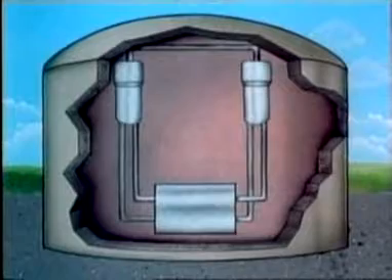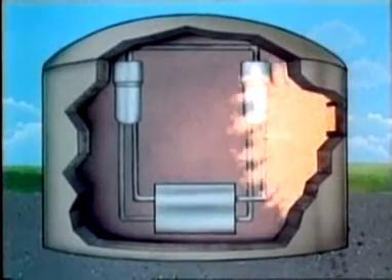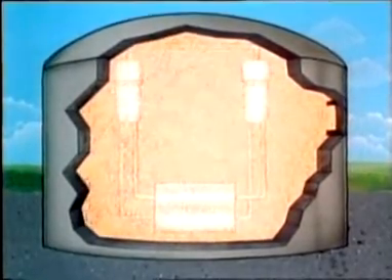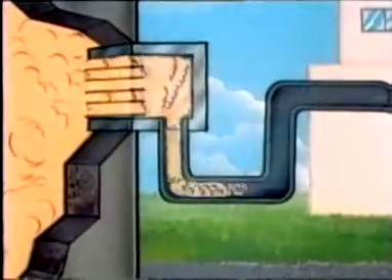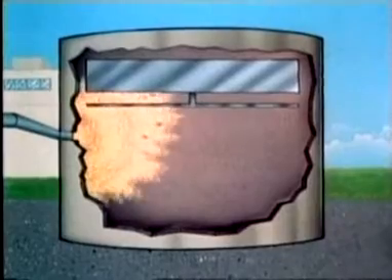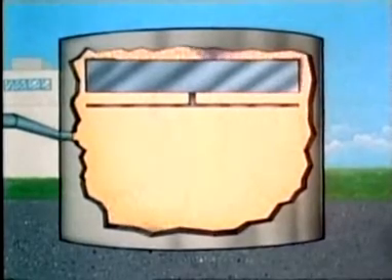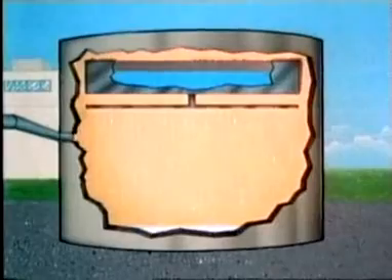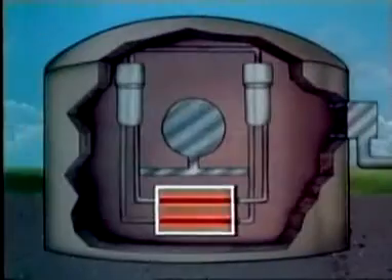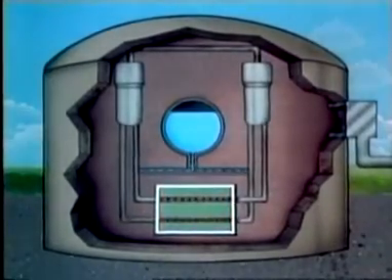One of the worst things that could happen to a nuclear reactor is a loss of coolant. In this Canadian CANDU reactor, the core is supplied with 2 water supplies. If one of these bursts, steam would escape into the pressurized building. The buildings in Canadian power stations are designed in pairs. From here, the steam would go to the next pressurized building and be condensed by a shower of water. The design varies in different countries, but the principle is the same. All reactors have large supplies of makeup coolant, which can be brought in case of an accident.